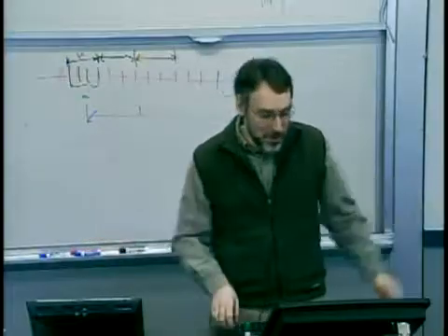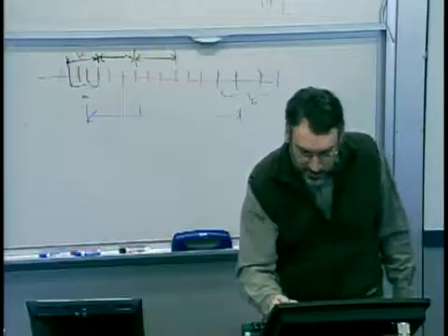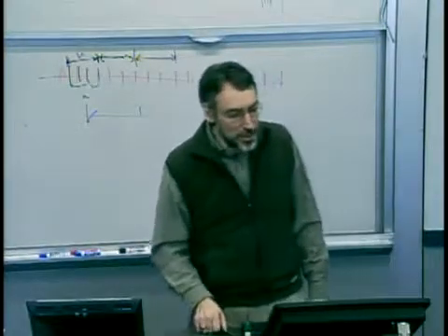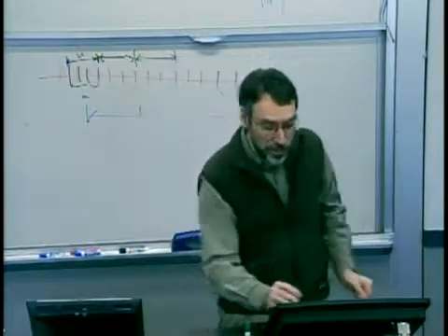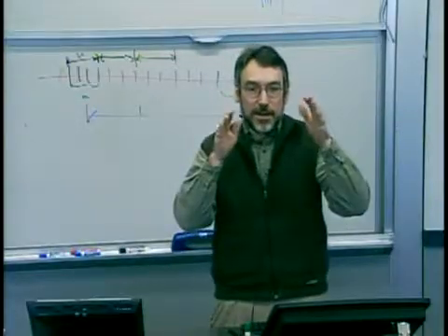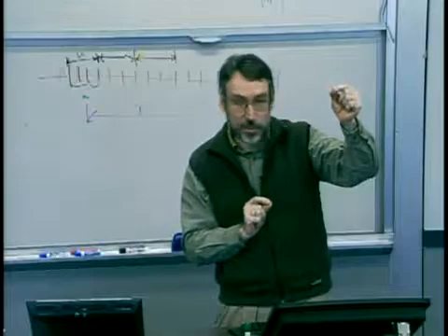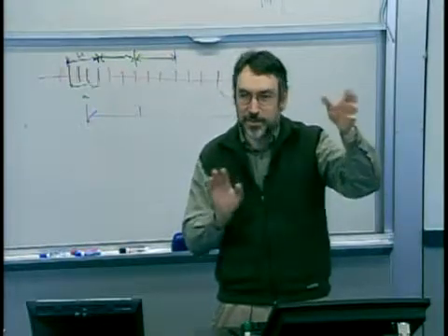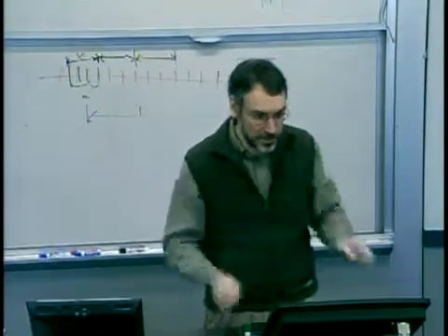So you don't know. It may well be I've got really tight spec limits. My parts really need to operate down in here. By the way, you also have to be careful because if these are based on N samples, the sample distribution is tighter than the underlying process distribution. So if you see spec limits also on your control chart, that's kind of a warning, because usually a control chart is based on sampling, right?